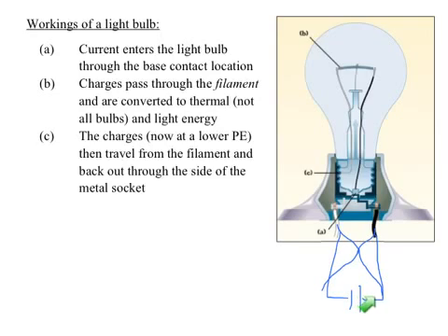The charge carriers would want to take the path of least resistance, and all this energy in the charge carriers would go like this, and it would come right back through. It wouldn't actually go into the light bulb. So this would create a short, and the bulb would never get any energy. And without some sort of a load-bearing element, these wires, and I'll highlight them in red, this portion of the wire that crossed would start to heat up, because it would use up all the energy in the charge carriers, and when this heats up, it would start to ignite, and you would have a fire. And that causes a lot of melted wires and simple house fires that you have from these short circuits when you have old wires where the wire rubber casing is old and deteriorating.